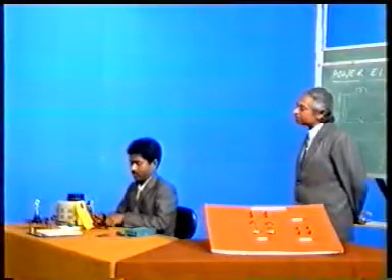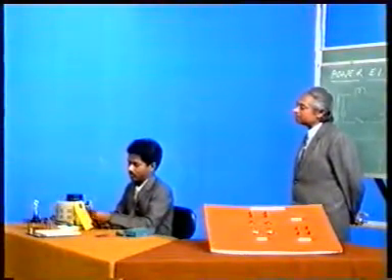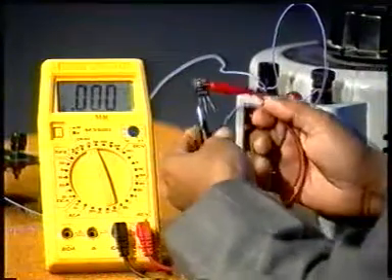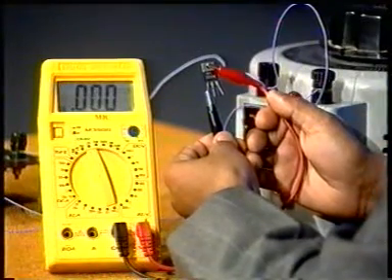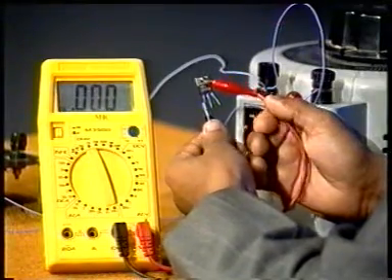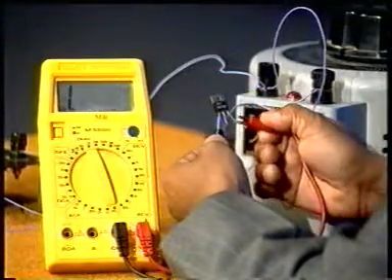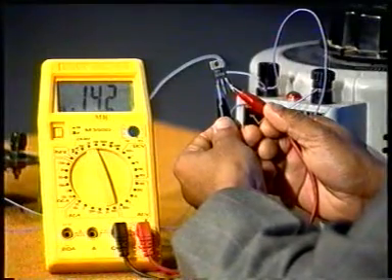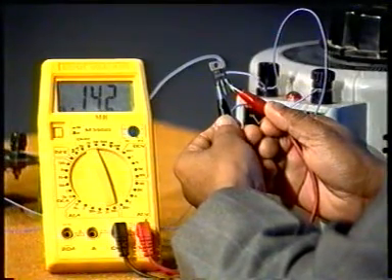There is one damaged triac and he is connecting it between T2 and T1, and it is showing 0 resistance. You see, that means T2 and T1 are short. Can you check it between G and T1? Yes. Please. So G and T1 is okay. You see, G T1 is okay, but T2 and T1 were short. Okay, thank you.